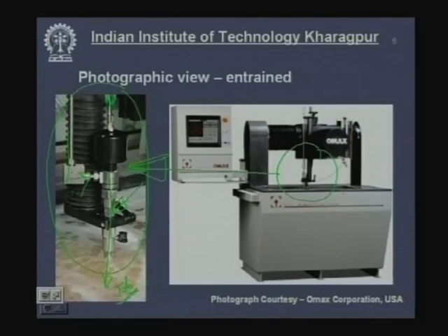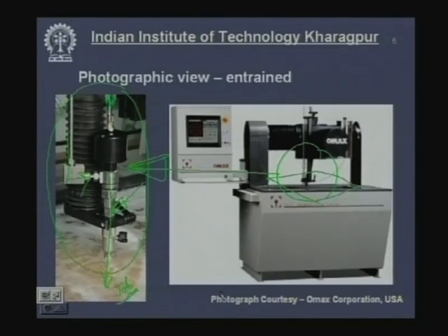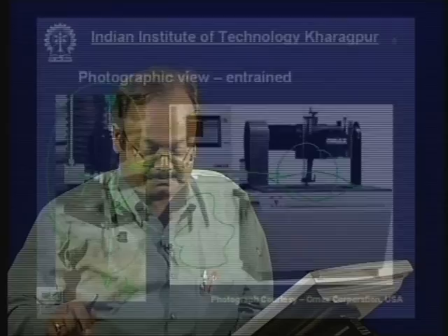The whole of this is nothing but the zoom view of this particular portion. So the cutting edge is this small. Below that you have your workpiece. This could be your workpiece which you need to cut possibly along a complex contour. So you need a CNC system. So this is the CNC system and this is the CNC table where the job is maneuvered to get a particular contour. Any contour you want under the CNC control, that you can get.